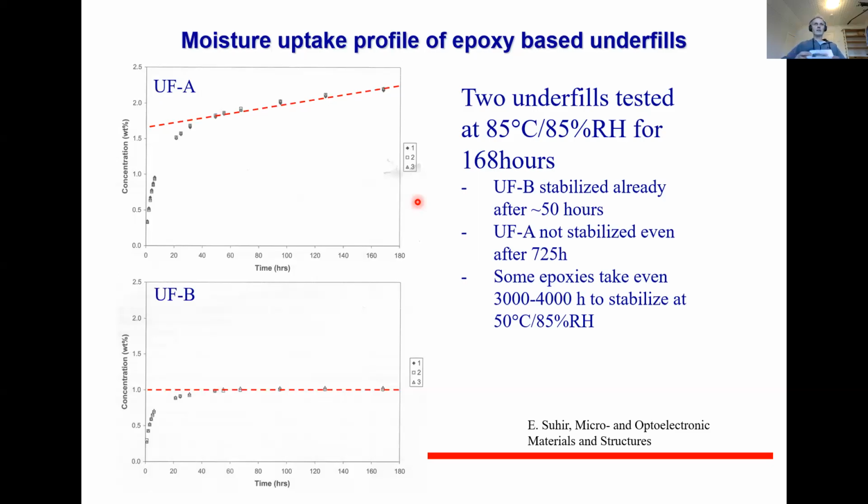And then their customer, the big N, had, let's say, qualification test procedures stating that all products which they are willing to purchase must withstand this normal 85/85 for 1,000 hours test. And then these guys from the smaller company checked, okay, the glass transition temperature is 90 degrees, so no problem. It should withstand the 85 test.